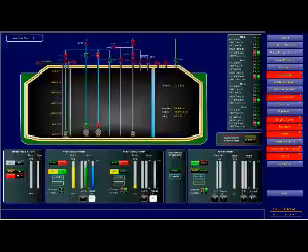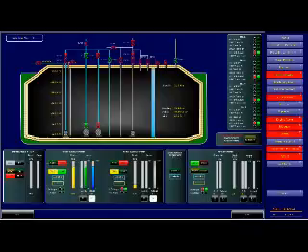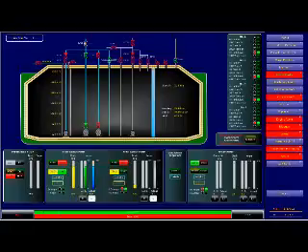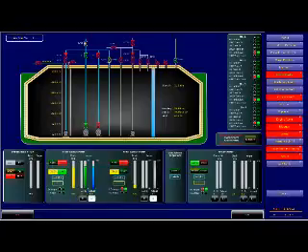Yeah, that is lovely. Now you can stop the recirculation pump. First we have to open it. Yeah, and then stop the recirculation, and the liquid will flow faster. And put the pumps on automatic.